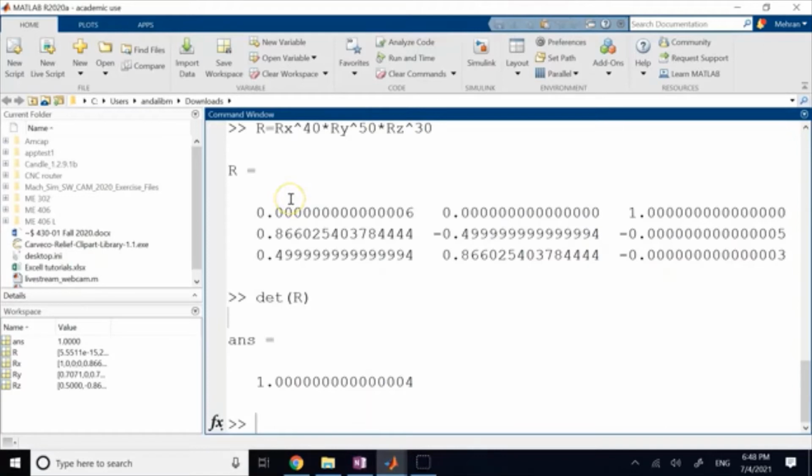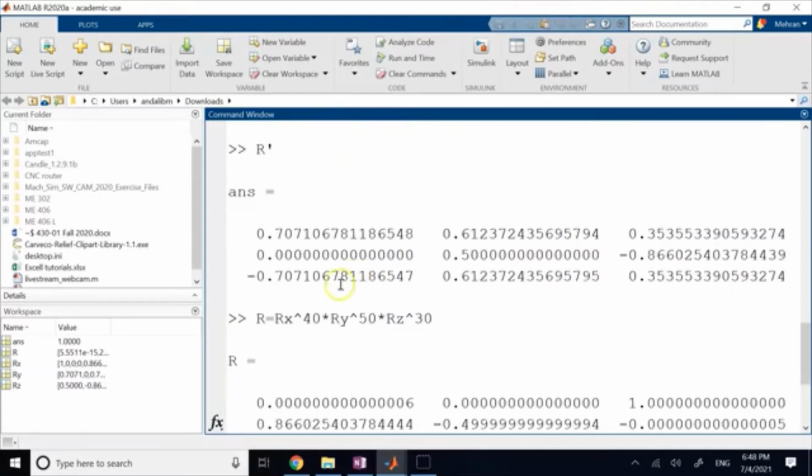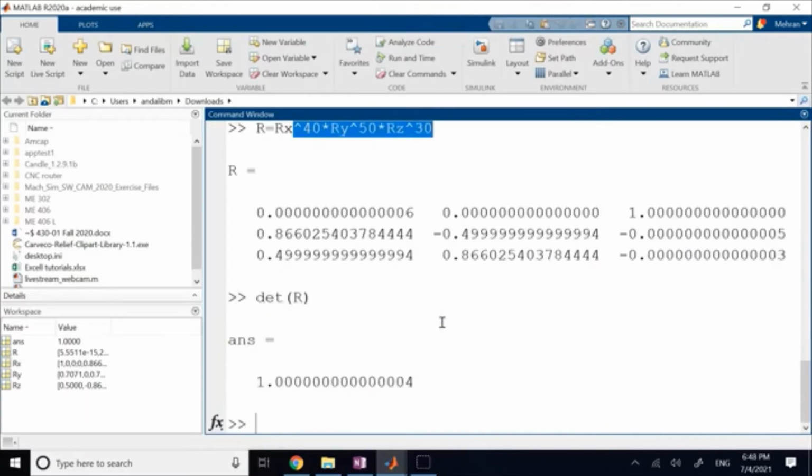Each time was multiplied by the previous one to get you the current orientation. So yes, in 2 seconds with that sample time of 10 milliseconds, if you're each time calculating a rotation matrix and multiplying to get your current orientation, you have already multiplied 200 of these R's together. So something like this, with like here 120 times multiplication, that's not really something so out of the ordinary.